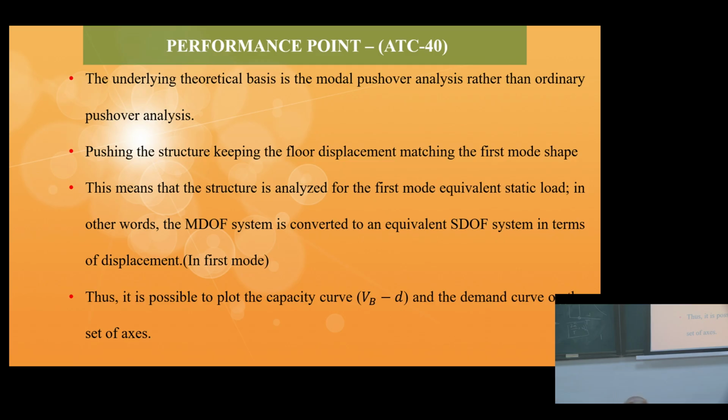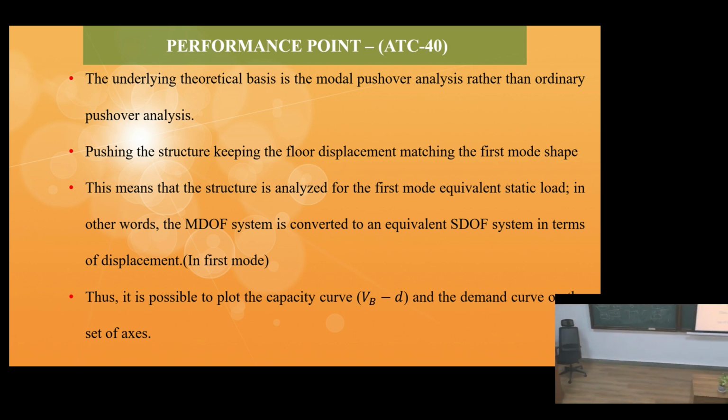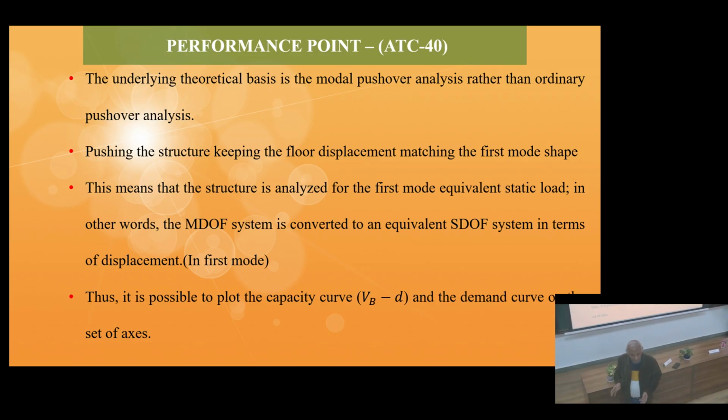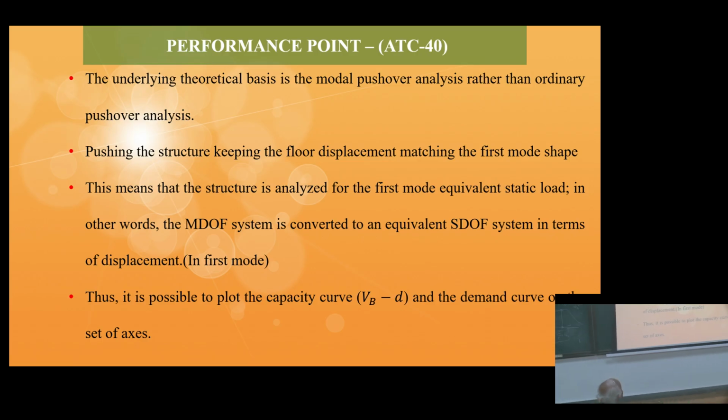That means for each mode of vibration, you can convert a system into a single degree of freedom system. And here, for the first mode of vibration, or fundamental mode of vibration, by knowing the mode shape and by knowing the natural frequency, you can convert it into a single degree of freedom system. That is what is done in the pushover analysis, CSM technique.